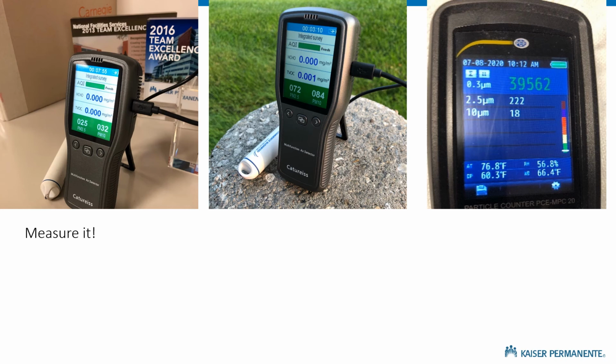The reading outside was 72 micrograms of PM 2.5. The reading indoors was 25 micrograms PM 2.5. That ratio of outdoor to indoor particles is about 1 to 3. That's pretty good. That means in my office building the filters are probably working fine.